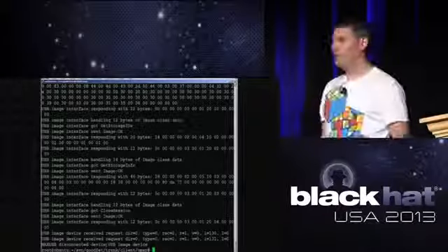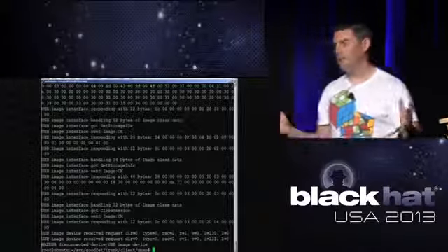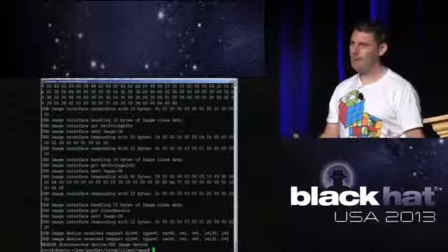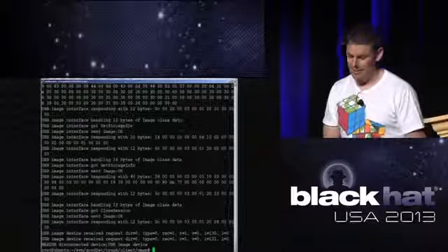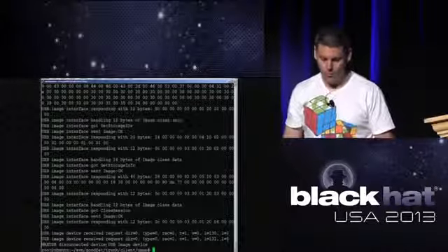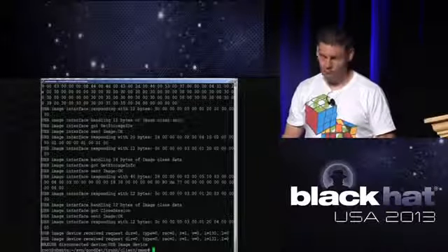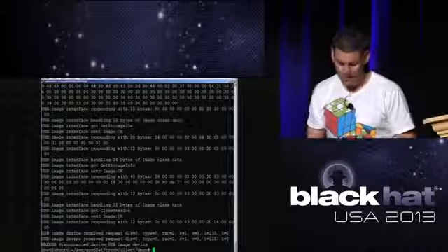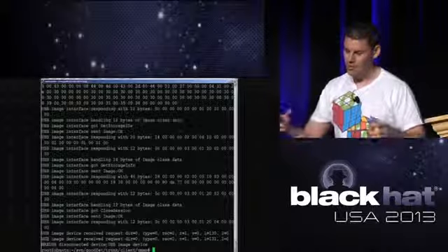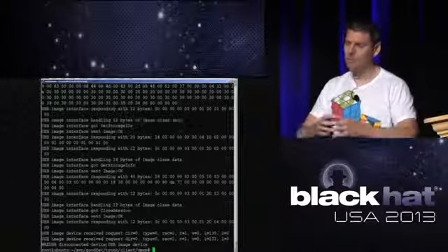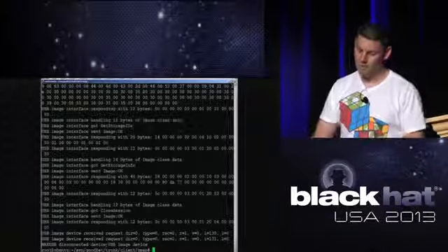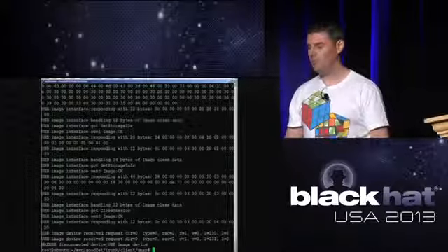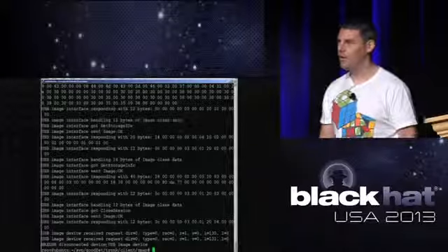I've mentioned fuzzing a couple of times. I've done quite a bit of USB fuzzing in the past, and this new capability that FaceDancer has given me provides the capability to do much more comprehensive fuzzing now. You identify what classes are supported, and then, rather than the mutation-based fuzzing that I've done in the past, you can look at the spec and implement all your fuzz test cases based on the spec for the class of device that you want to fuzz.